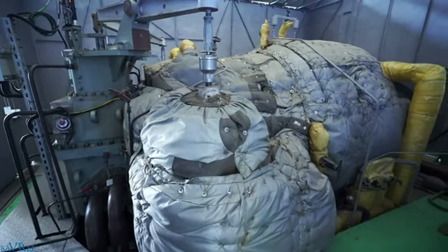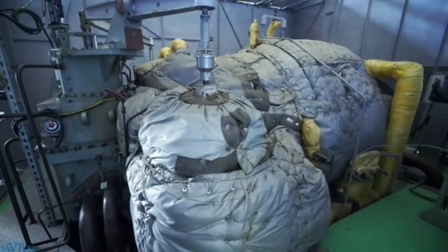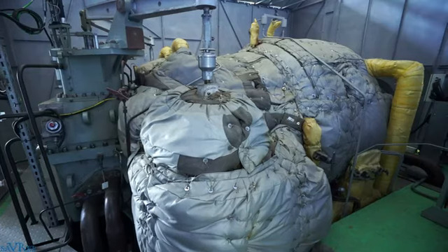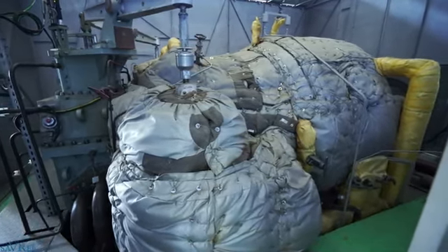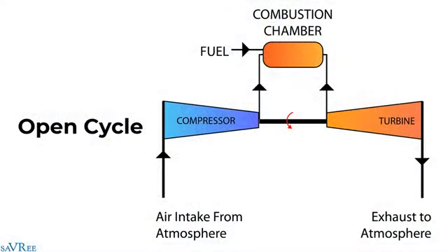The other type of turbine that you may have seen is a steam turbine. Steam turbines require steam to operate, that's the working fluid. Gas turbines require a gas. It may be air, but there are other gases that you can use as well. It really depends upon the system. One type of system is open and one type is closed. In this video, we're looking at an open type system, and that's the only type of system that we're going to discuss. Open type systems use air, ambient air, from the surrounding environment as the working fluid.